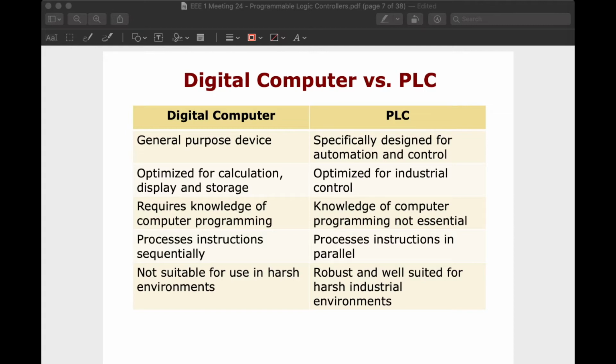So when you put the program there, the PLC scans all of the code and then runs it in parallel, while most general purpose computers are designed to run operations sequentially. Although you might not be familiar with this, computer engineers or computer scientists might be. But you just have to remember that the tasks or operations are performed in parallel by the PLC.